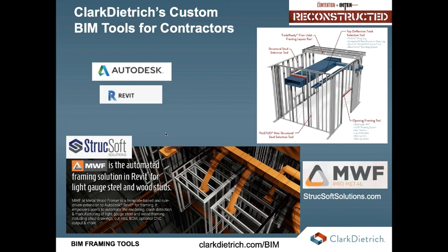So you could take a 1/2-inch opening tolerance around the ductwork, put a header across the top of it. We've got some great custom tools that our teams customized. We put them into the MWF system itself, and allowed everybody else to start using them too. So it's got our typical headers in it, a lay-in header, box header, red header. All those products are in there to actually frame from, and you can select your headers and your jambs. And again, the MWF system helps with the tolerance. So if it sees a clash between trades, it'll help give you a tolerance between those and actually throw an opening in there for you too.